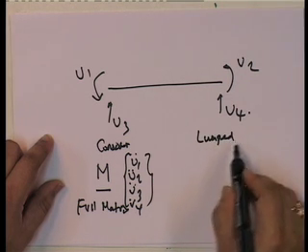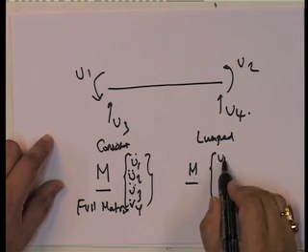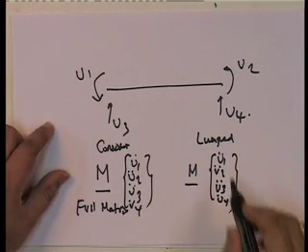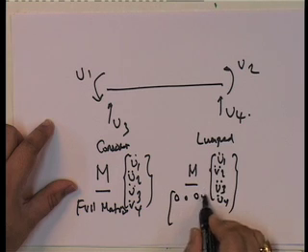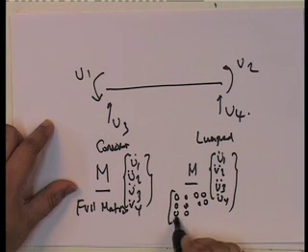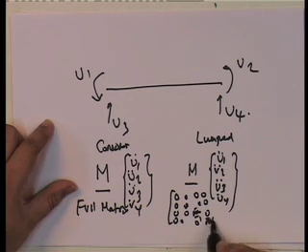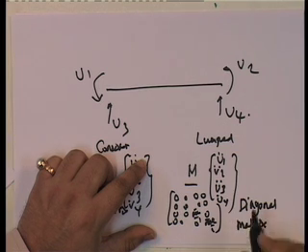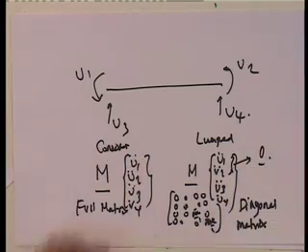Lumped M: since a lump mass is lumped at these two ends, V 1 and V 2, it is completely 0, and the only thing that we have is, so it is not only a diagonal matrix, but corresponding to these two, it is a 0 matrix. So the entire lumped mass, I want to keep on emphasizing this point, because it disturbs me today to see that people do not understand where the lumped mass formulation came from, and they continue using this lumped mass formulation for situations where it is not valid.